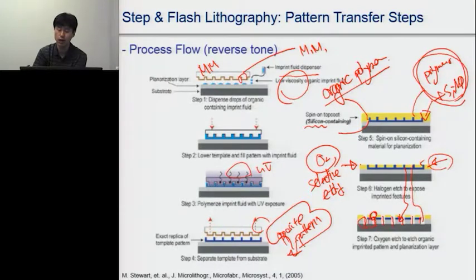That different etch rate makes a selective etching on this blue area only, and then it can make the trench structures, these nano cavity structures, only on this blue area. So that is the secret for transferring two different tones of patterns using one single master mold.